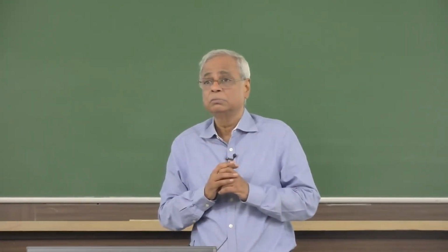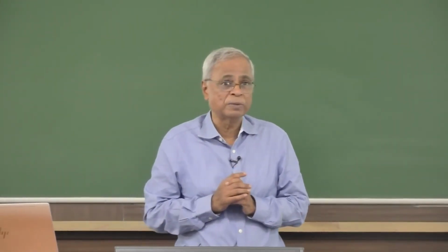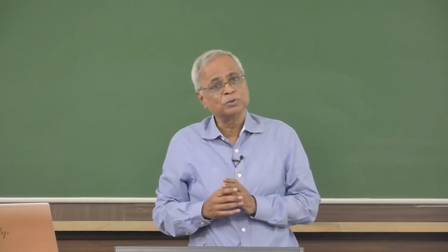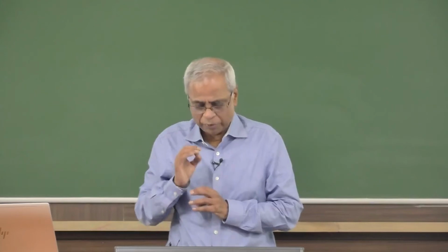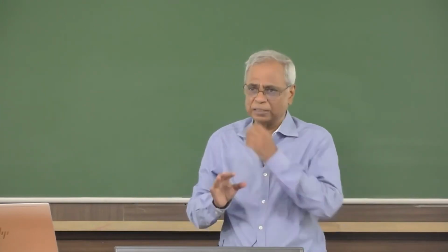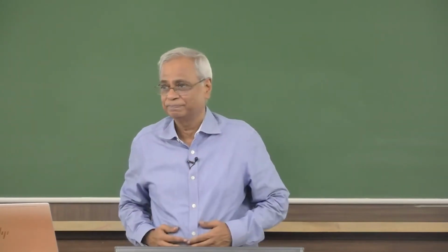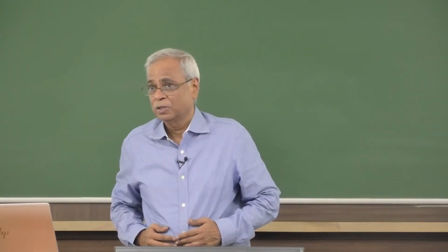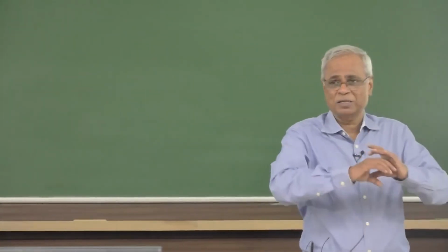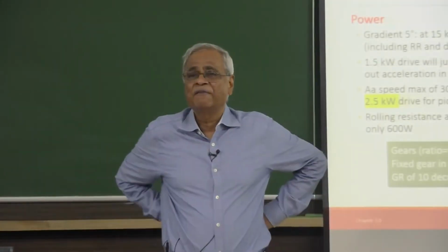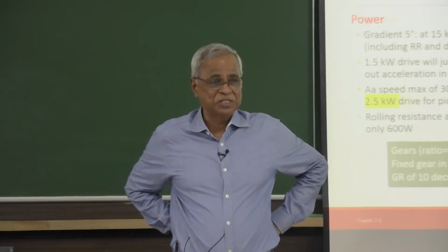Peak torque can go up to 7 Newton meter, and with the gear it will give you 70 Newton meter. So, that is how it is designed. We will talk about gears more in another chapter. So, the term used for gear, gearbox, clutch, everything in a petrol engine, IC engine, is transmission.